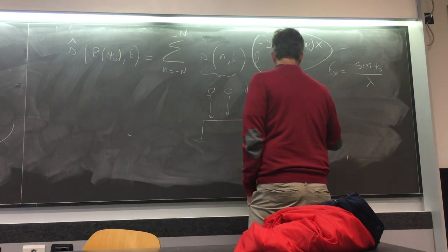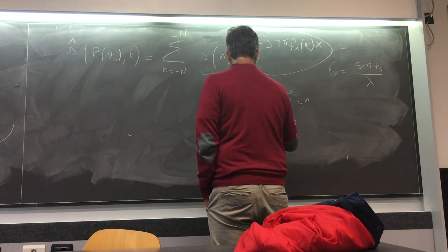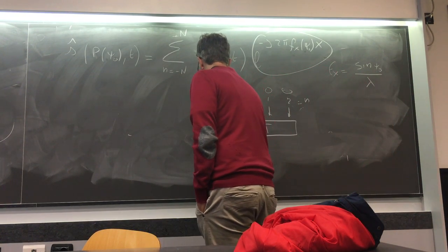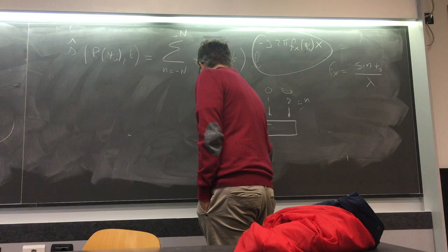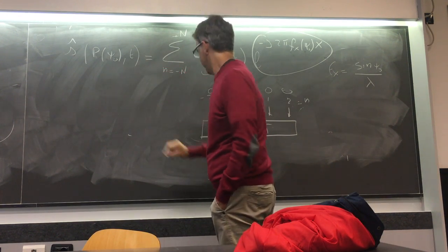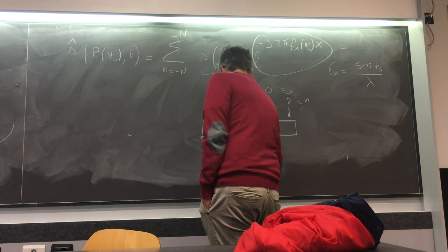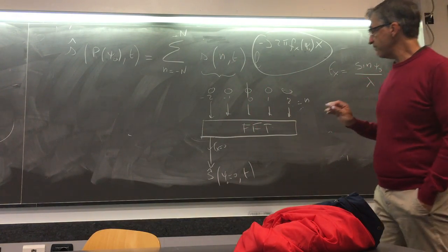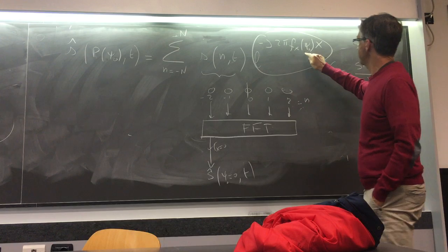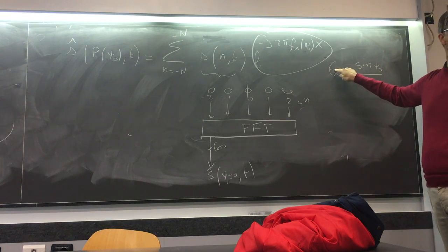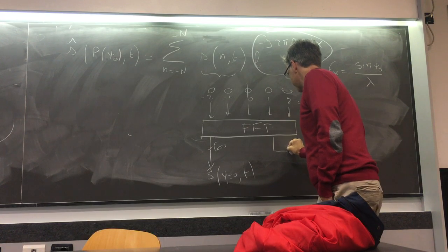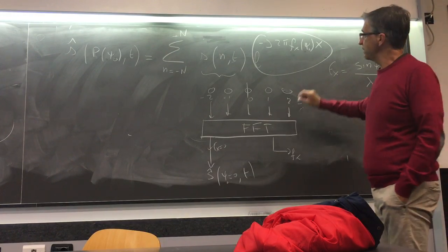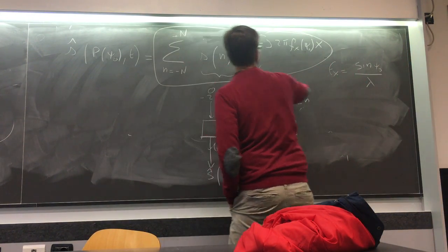So I put all this signal in a block that time by time provides the Fourier transform, and the output at fx equals 0 is the estimate of the signal here, estimated at psi equals 0, for all the time. Okay, you understand? If I wanted to look at the signal in another direction, I just change the value of fx. So in general, the Fourier transform gives me the component at a particular fx. But the Fourier transform actually does this operation.